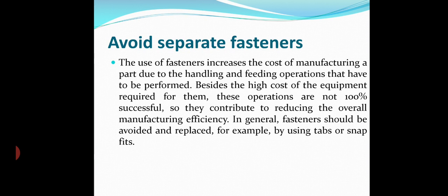In general, fasteners should be avoided and replaced by using tabs or snap fits. Snap fit is an assembly method used to attach flexible parts, usually plastic.